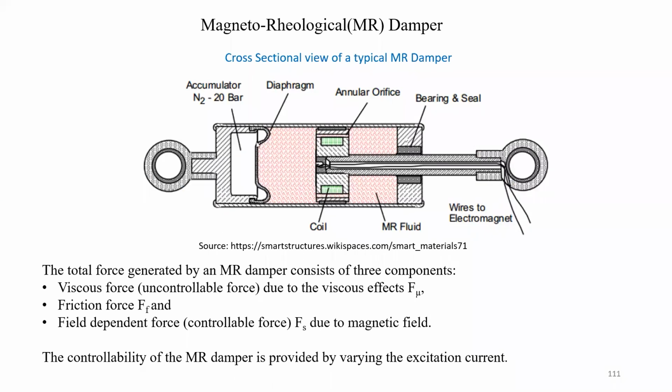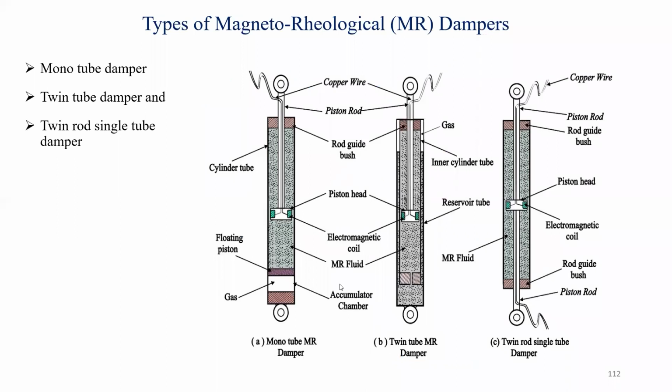We have also designed this MR magnetorheological damper, that is a twin tube damper. This is a single tube damper, a monotube MR damper. That means there is no passage for the oil to go in, unlike this twin tube. As soon as it presses, it passes through this orifice, goes back and fills from the other side. This is the twin tube MR damper, and this is the twin tube damper we have also developed. Actually, we developed this twin tube MR damper long back.